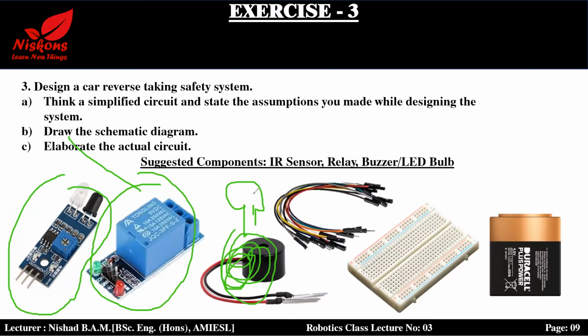That is a little bit complicated, right? That will be learned later. So you can simply put one bulb, and if the sensor detects, you can design the circuit, right? Of course you have to have some jumper cables, but a breadboard is not necessary, right? If you have a breadboard, you can design it with that. If you don't have it, you can do it using only jumper cables, right? You have to have a battery also. So that's all about the hints. It's up to you now.